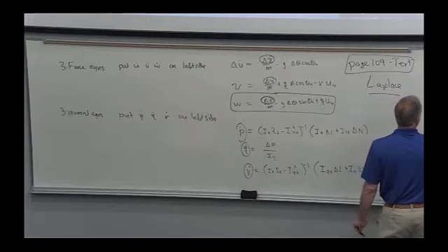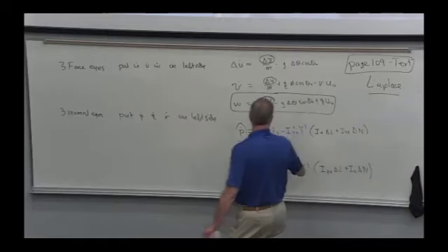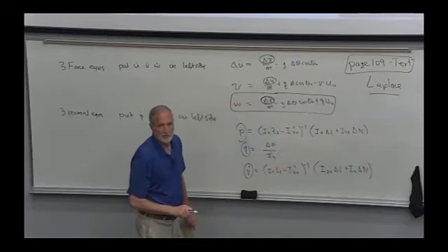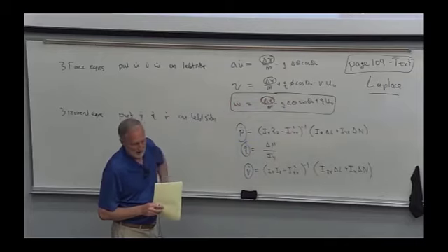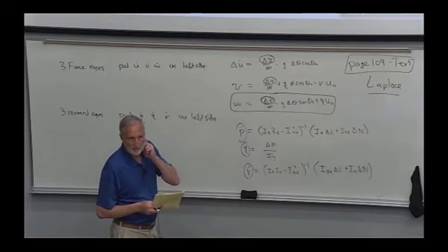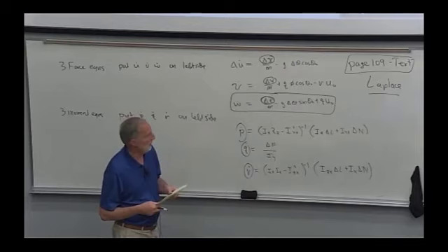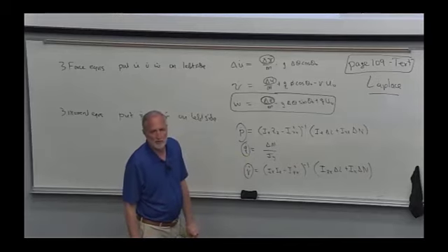And we can separate these out into longitudinal and lateral directional because the equations don't couple together between them. And we saw that when we were doing trim, right? We could solve the lift and the drag and the pitching moment equation separate from the roll, yaw, and side force. And aerodynamically, the airplane's decoupled that way as well.